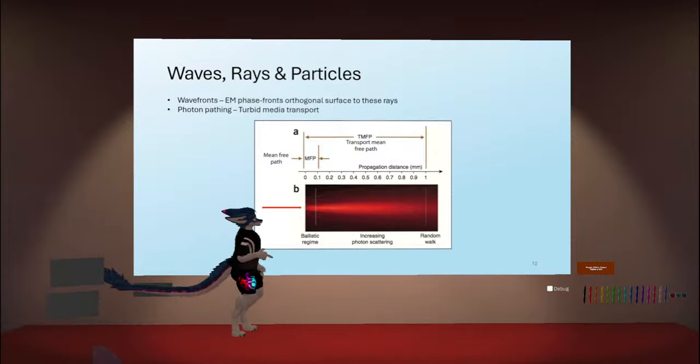And you generally have two regions here. You have your ballistic region, which is where everything behaves like you want it to. You have a quasi-ballistic region where you're scattering, but you're still getting a lot of forward scatter. So as long as you don't care about maintaining this perfect ideal waveform, you have pseudo perfect waveforms still.